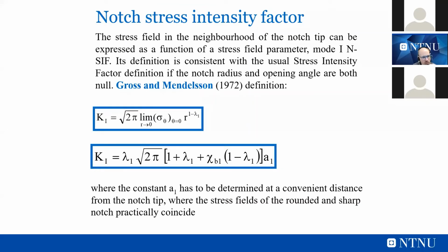What is also important to mention, as I mentioned before, is that the stress concentration factor is not a parameter that you can always use. When you have a notch radius that is small, or tending to 0, you have to actually leave the point method, the method where you are only considering the peak stress at the notch tip, and go in the direction of the notch stress intensity factor, which is an extension of the stress intensity factor that we use in fracture mechanics. This is a field approach, so we are measuring the stress field ahead of the defect, the crack or the notch, not the stress at the tip of this defect. And we are evaluating a field parameter that is able to describe the stress intensity in front of this region.